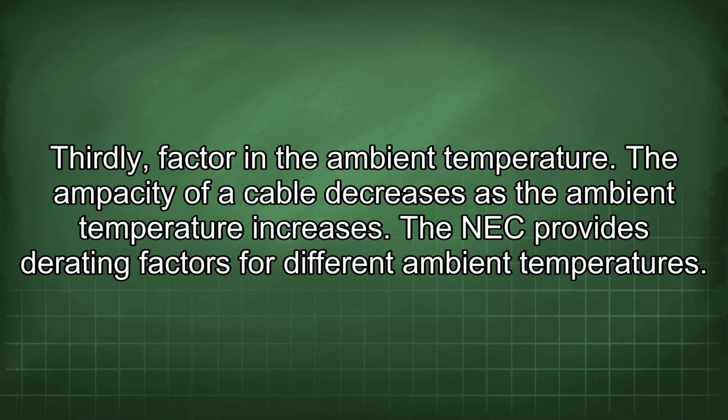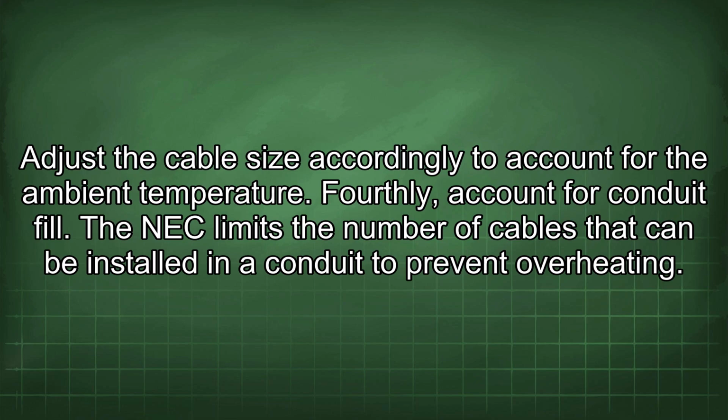Thirdly, factor in the ambient temperature. The ampacity of a cable decreases as the ambient temperature increases. The NEC provides derating factors for different ambient temperatures. Adjust the cable size accordingly to account for the ambient temperature.